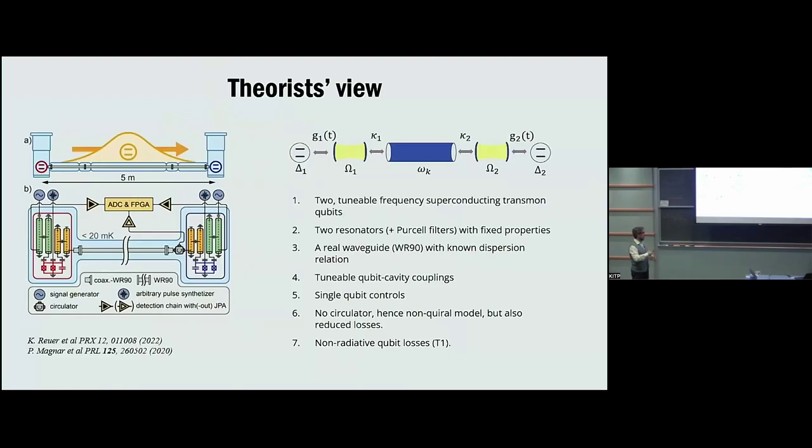You have first to get very good impedance match to the waveguide, and that in this case is challenging. And then you may risk having internal reflections or resonances that you don't want. If it's not a matter of resonances, but just distortion, further distortion, I think that can be compensated. But if it's really something that can create pseudo modes around there, that can be challenging. And these are things that can spoil the fidelity of transfer.